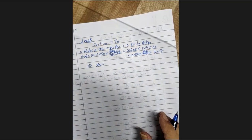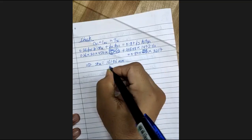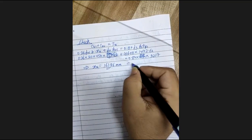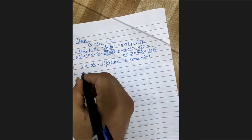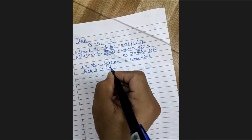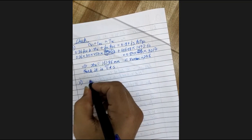Others, is that correct? Yes, the same. 161.86 mm. So XU is found, and now it is clear it is less than XU max. How much was XU max? 276. Hence it is an under reinforced section. The first check is done. Now the second check, let us check MR.